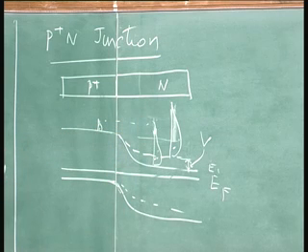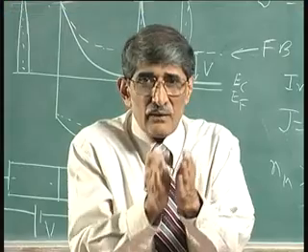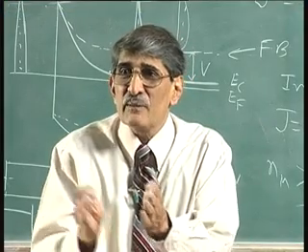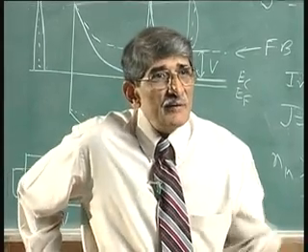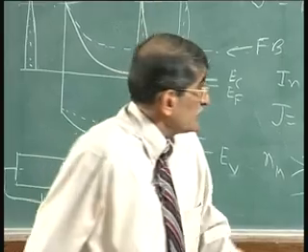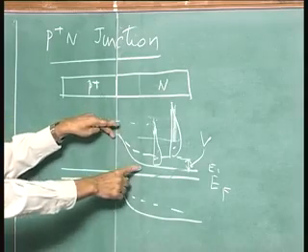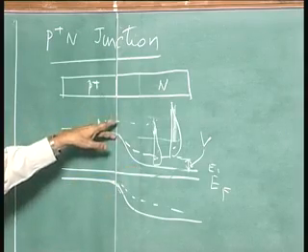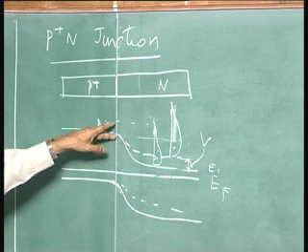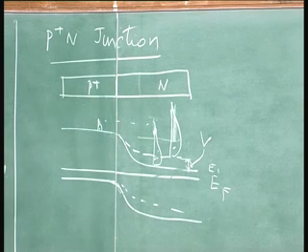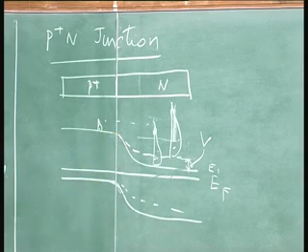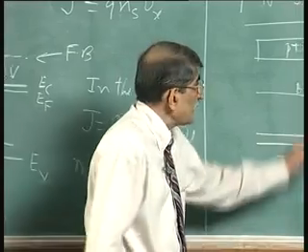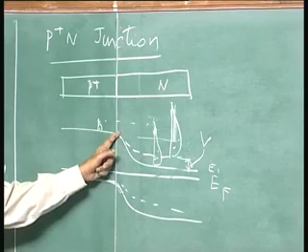So, if you give a chance to those electrons to be removed away once they are injected into the P region, the same way that is done in the case of the metal, the current will be exactly that. Supposing this barrier height is the same as the phi bn that you got in the Schottky barrier, you would have got the same current. But if this barrier height, which is the built-in potential, is the same 0.75 volts, the current that you will get will be much smaller than that for the same voltage, because